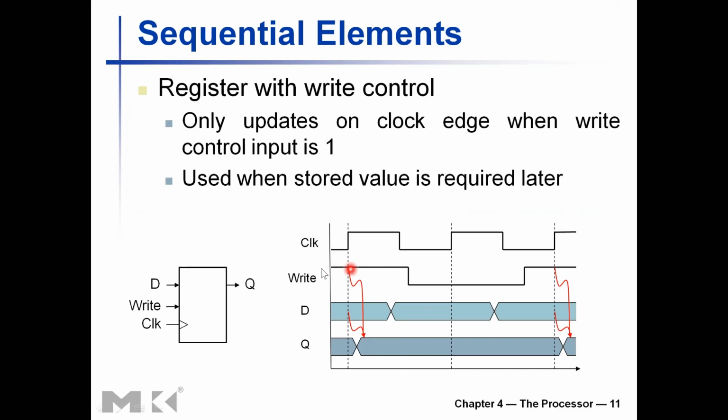You can see that the write signal is used to decide when to write into the memory, right? So at that clock edge, if the write signal is set high, you take the data from the D input into the Q state, into the state of the latching mechanism at the memory. That is the idea. So if the signal is 0, you don't write.